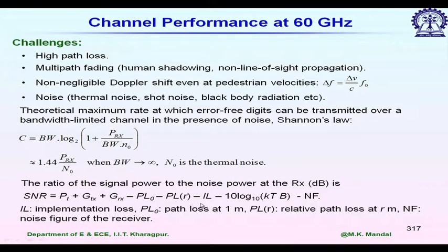Next is the IL. We call this implementation loss. It represents all the losses in cables, antennas, etc. Then we can calculate the noise contribution. We are calculating SNR, so we are now subtracting the noise component.